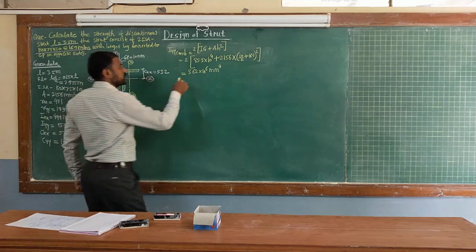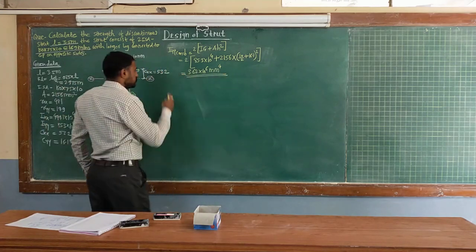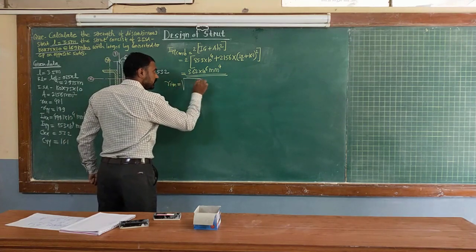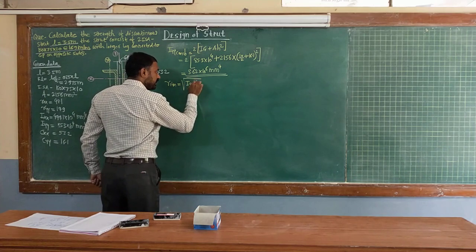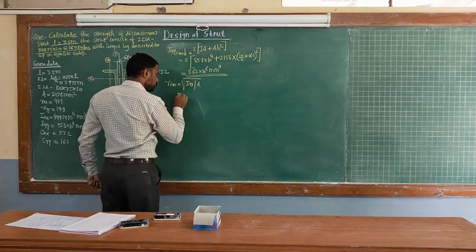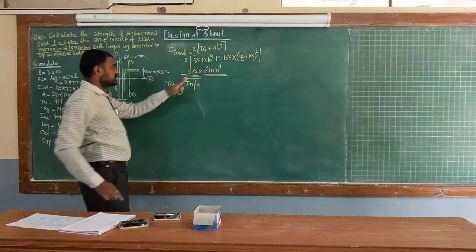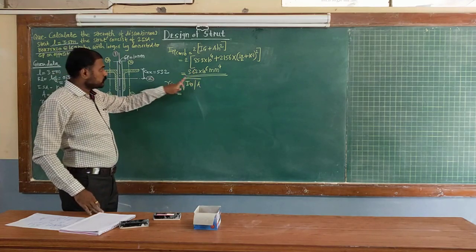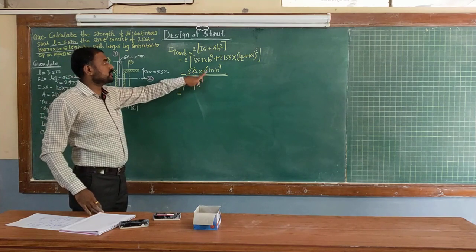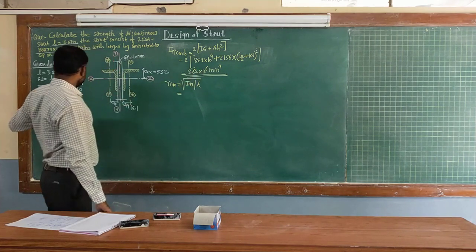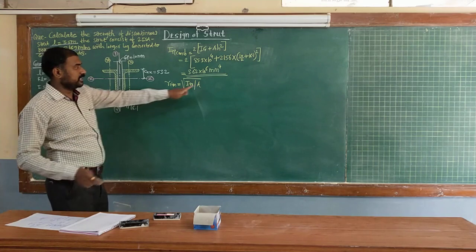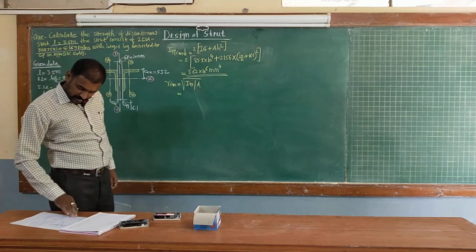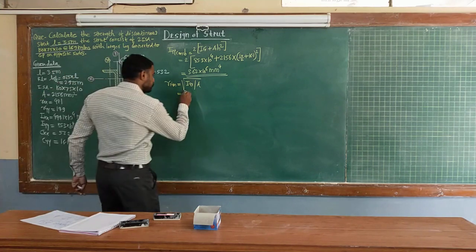So combined moment of inertia. So this will give us what? R minimum. So R minimum is equal to under root of IYY calculated divided by area. As this moment of inertia is twice, area is again going to be multiplied with 2, correct. So under root of 3.62 into 10 raised to 6 divided by your area is 2156 into 2, double area. So R minimum I am getting value as 29 mm.